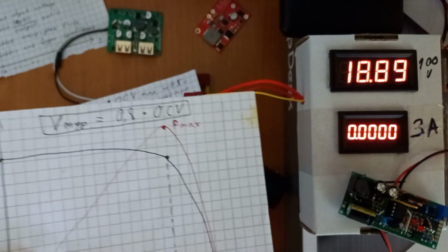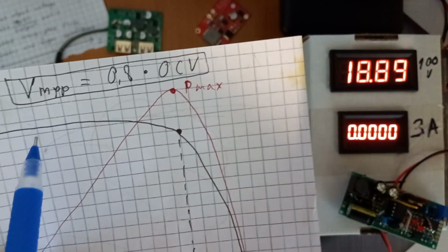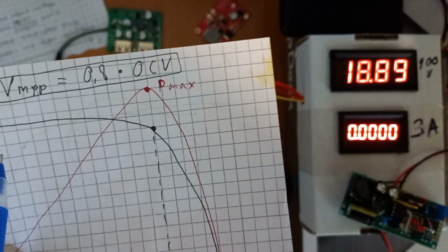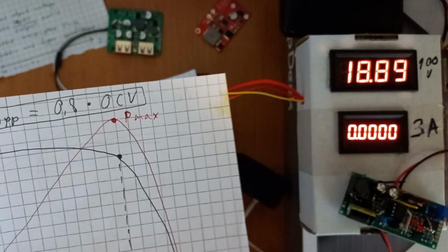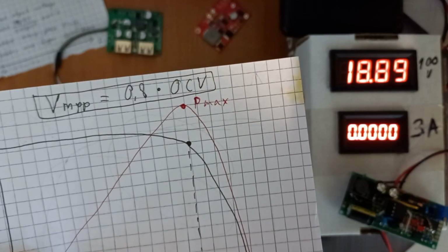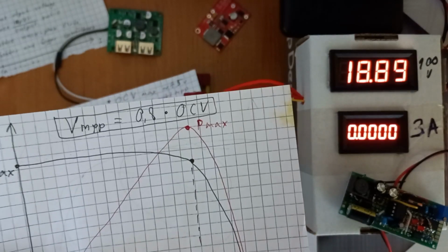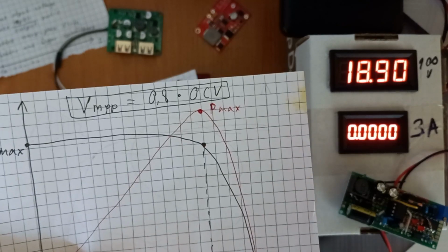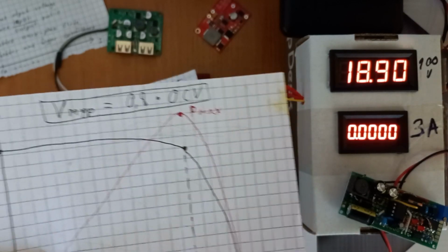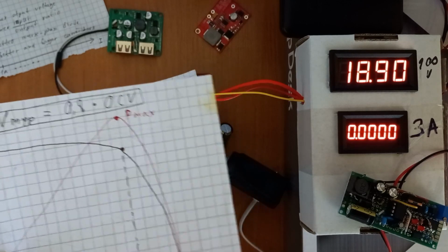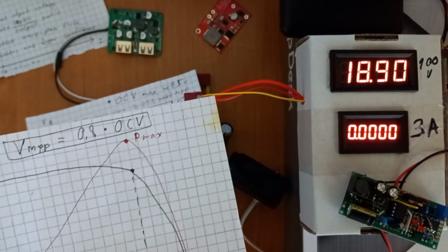Additional corrections are, on lower voltages, there will be actually slightly higher current, up to some 5%, so instead of 50%, it's like rather 45% improvement. And then by fact, with 18 volt rated panel, you won't likely receive 18 volt MPP and rather 16.5 or something, as it would require cooling. Solar heats up and drops voltage by some 7 to 10%. And correction for conversion efficiency of DC-DC buck converter. That will take away some 5 to 10% more. I'll explain in next chart.